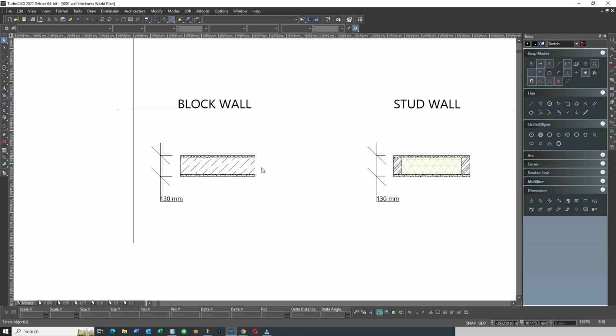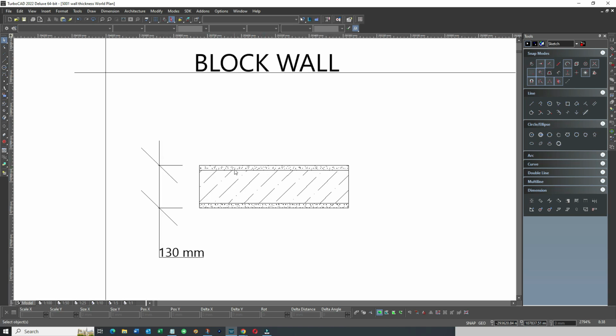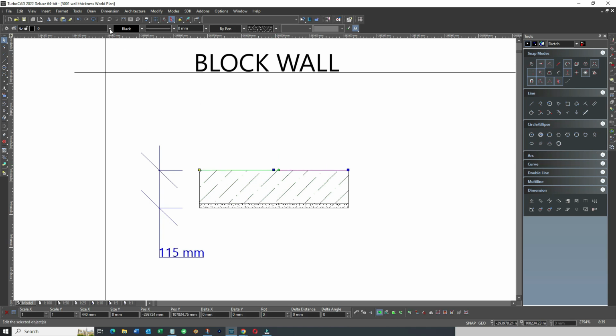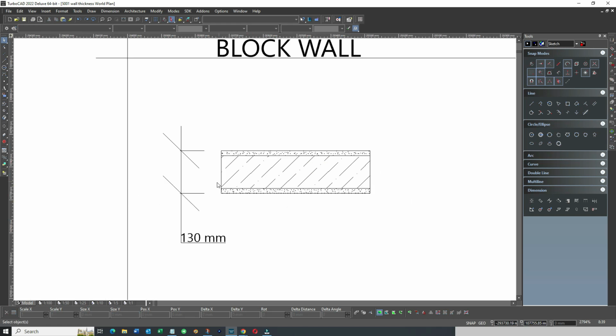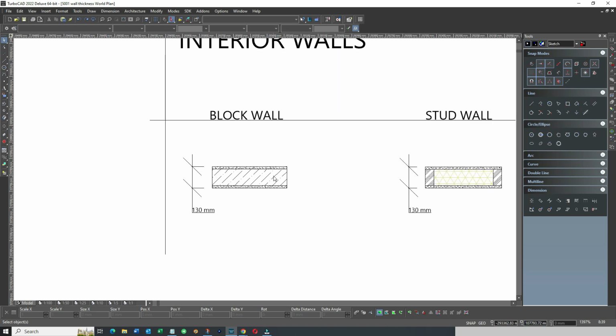So if you're on the ground floor and you're using a block, you've got an allowance here of 100, and then plasterboard, dry line. But again, if the bricklayer is rubbish and the walls aren't straight, then the dry lining can in fact become 50 mil rather than what we've allowed for, plasterboard, which is 12.5 and a little bit of skim on the top. In fact it could end up being 30 mil. But 130 is a fair representation for an internal block wall with a little bit of boarding on either side, that's been done reasonably, in good quality or decent standard.